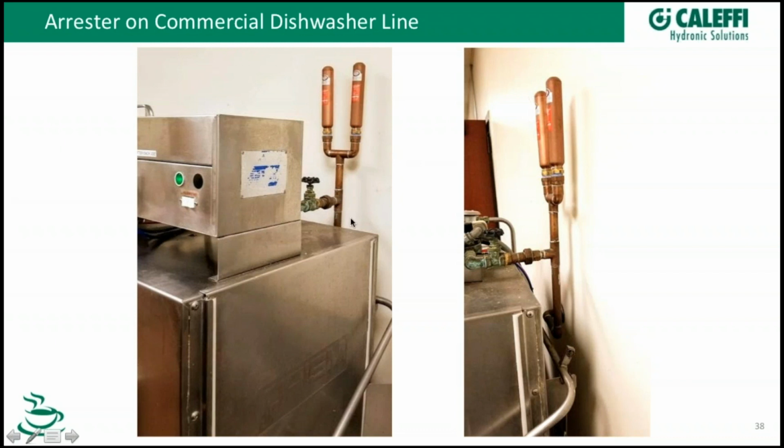And by the way, these water hammer arrestors really want to go as close as possible to where the water hammer is being generated, because I've had people say, well, can I just put a water hammer arrestor next to my backflow preventer? I said, well, it would do a better job if you put it out where that water hammer is being generated at the solenoid valve, which is what he's got going on here, really close to where that valve is going to shut off. So he's going to catch that hydraulic shock wave right here close to the thing. If I put this back at where the water came into the building, now I got that shock wave continuing down through all my piping, and I've seen piping actually blow apart from a shock wave like that when they shut off a main and the water main jumps right out of the street because they shut off a 300-pound main quickly and just bang that shock wave through the whole system.